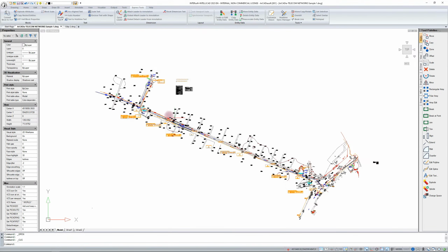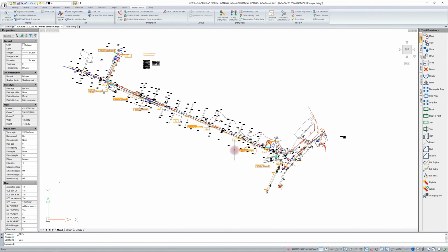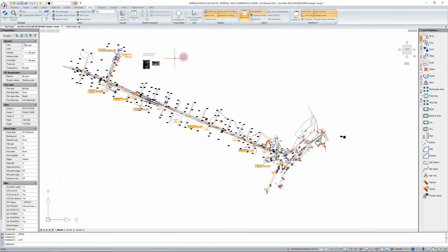Now I would still like to show you an option which comes in very handy. I'll just open a sample project. We go to the View ribbon and turn on Properties, because it will be handy for us. Often users ask for options to find something in the document. We have right here in the Properties window, on the right side, Quick Selection.